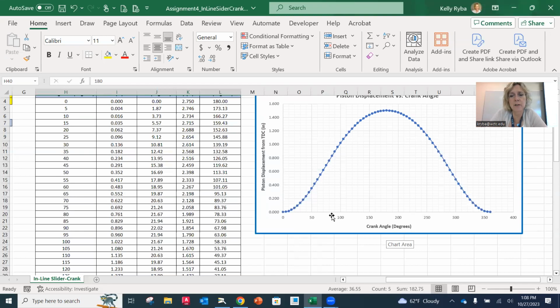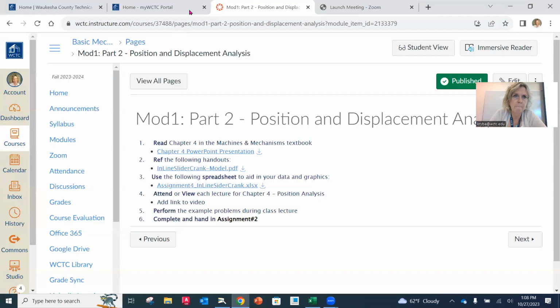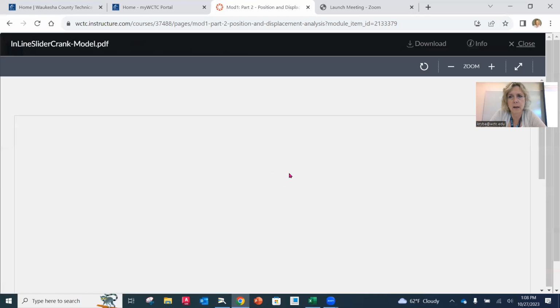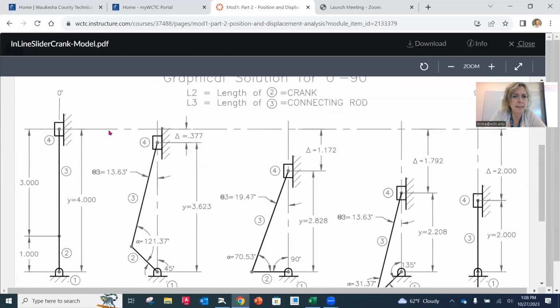Okay. And I like to imagine that this line right here is my 0 degree reference. If I go back on that diagram where we had the sketches, this is 0 degrees right up here. And so you're plotting this distance each and every time. It's always a reference back from 0 degrees. It's not the difference between the last movement. It's back from your initial 0 degree angle. That's the value that you plot on that displacement diagram.